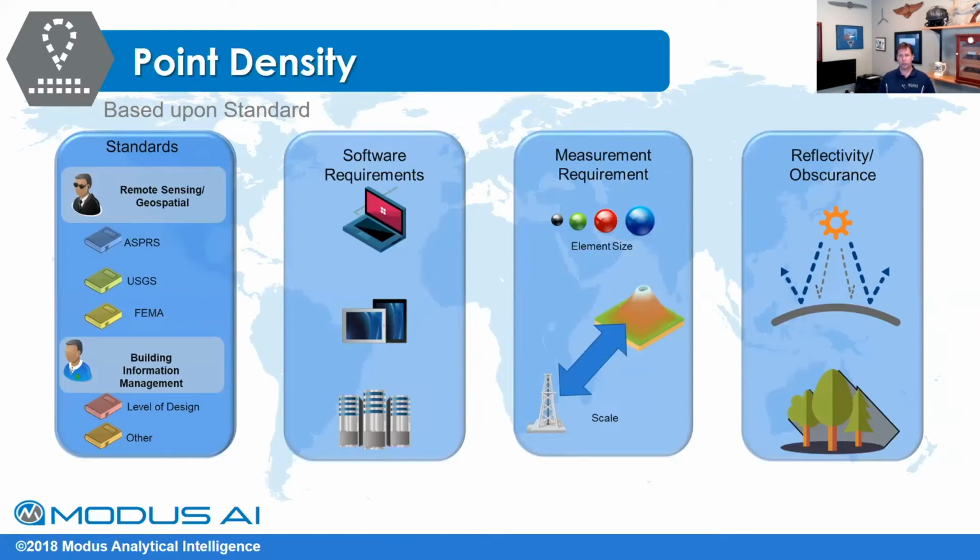it also is largely based on reflectivity. So, bare earth, I may be pulling 350 points per meter squared, which is really good. But now if I get into vegetation, I'm down to 70 points per meter squared or 35 points per meter squared, depending on canopy. And if I'm trying to do limb size versus, let's say, a cable, a 3 centimeter limb will have the same reflectivity as a 1 centimeter cable. So again, it comes down to what's your application to get the results that you need. We already talked about reflectivity.